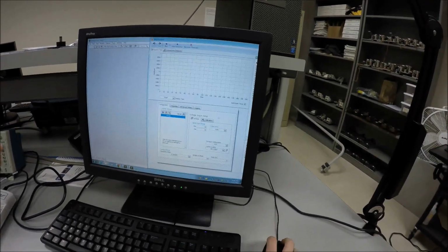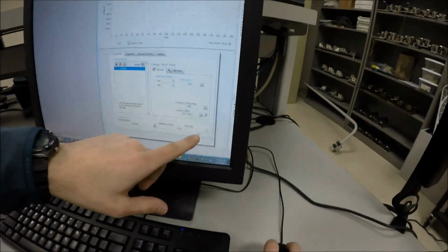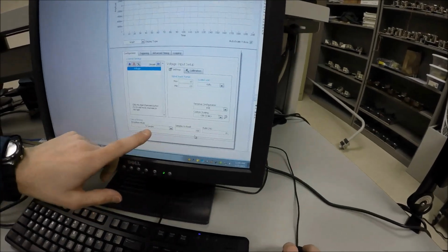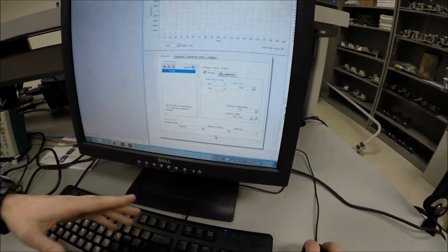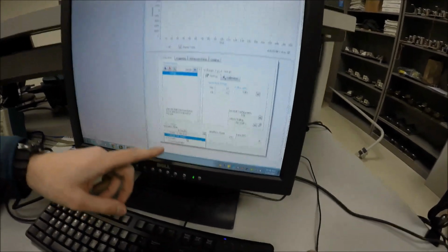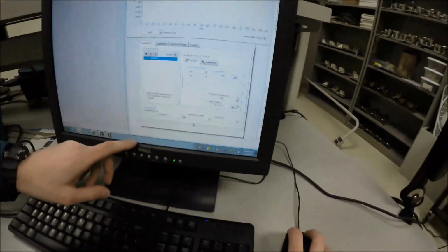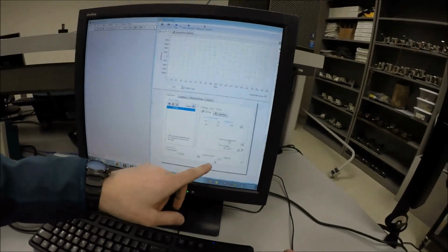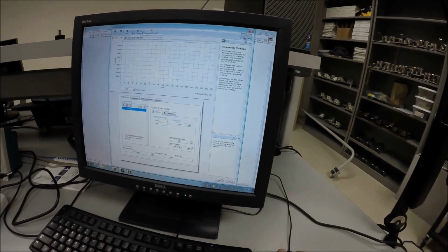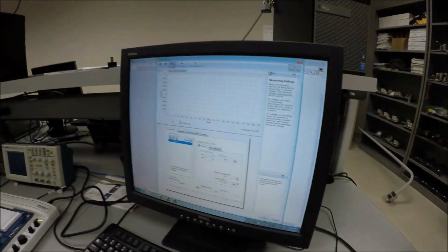Now it brings up the properties. Down in the bottom right-hand corner, we have the sampling rate, the number of samples to read, and the acquisition mode. For this laboratory, we'll be doing N samples, where you can also choose continuous or 1 sample on demand, the other two that we'll use throughout the lab course. But we have the N samples, samples to read, and the sampling rate. Once that's complete, we can test it by pressing this run arrow up in the top.